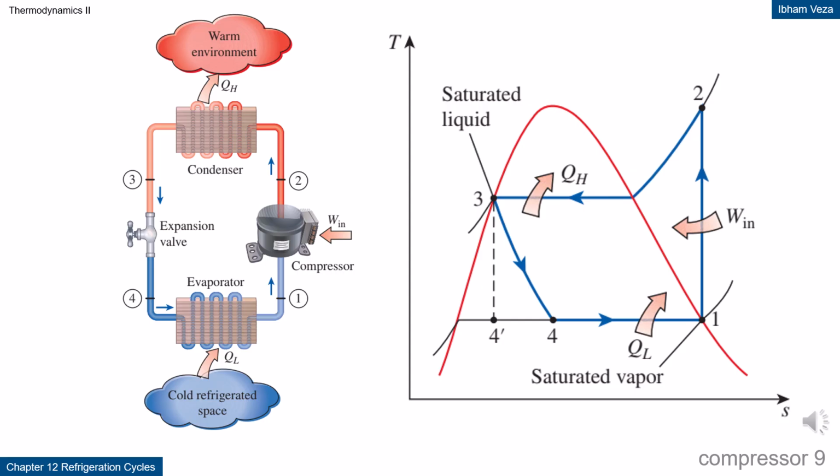Vapor compression cycle. This figure shows the vapor compression cycle, which is the most widely used cycle in real applications. Unlike the Carnot cycle, the expansion process is done using an expansion valve instead of a turbine. This introduces irreversibility, but makes the system much simpler and cheaper. The TS diagram shows superheating and phase change of the refrigerant. This is a compromise between efficiency and practical design.